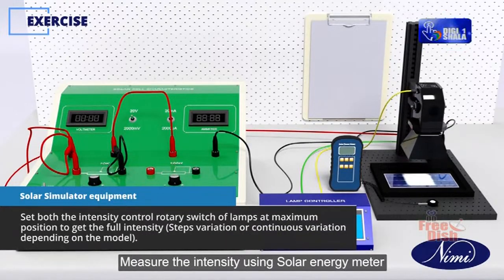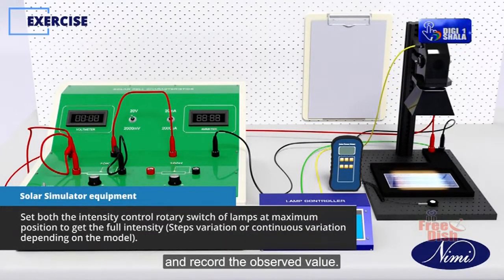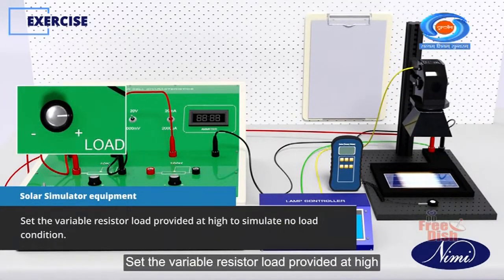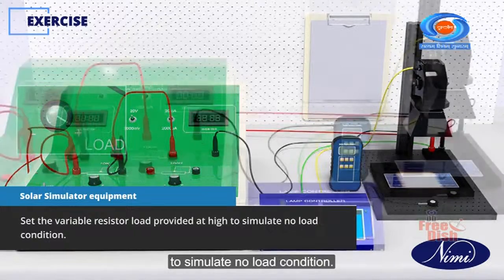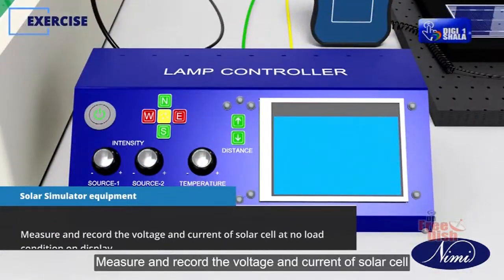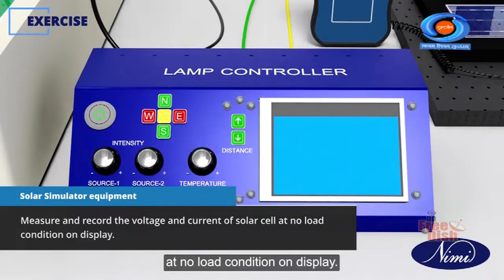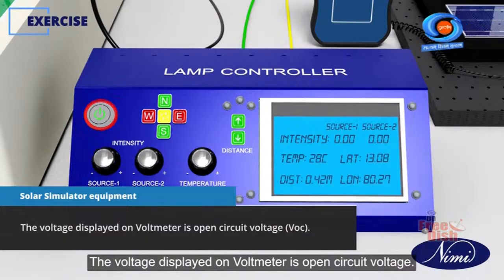Measure the intensity using a solar energy meter and record the observed value. Set the variable resistor load provided at high to simulate no load condition. Measure and record the voltage and current of the solar cell at no load condition on the display. The voltage displayed on the voltmeter is the open circuit voltage.